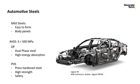But looking at steels in the automotive industry, typically you'll see mild steels used in cars where you need parts that are easy to form. So in the body panels, for example, these will typically be made of mild steels for formability. There are specific types of steels called advanced high-strength steel, or AHSS, and in these steels, the strengths can exceed 500 megapascals and can even get into the low gigapascals.